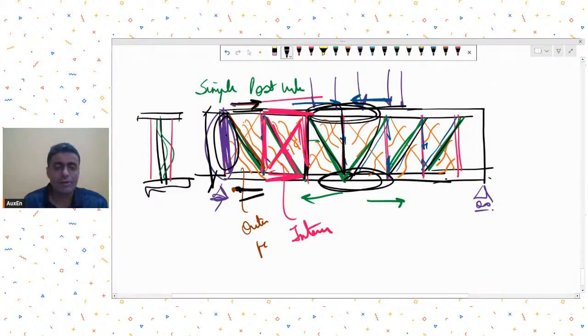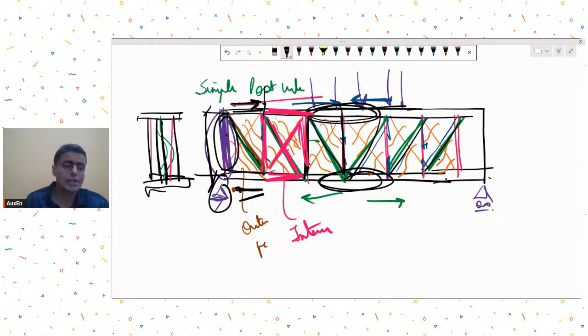Now if you have a double stiffener system, that means stiffeners on both sides, then both stiffeners have to be checked for taking the bearing loads at the support points and also these anchorage forces. If there is only one stiffener, then it has to take the bearing reaction and also the anchor forces.